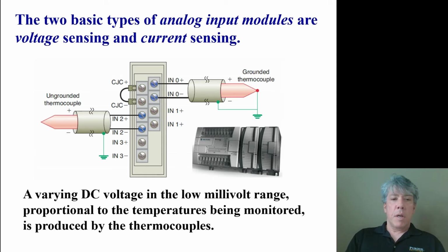It has to match. Now, sometimes the analog signal itself is converted at the PLC, sometimes it's converted somewhere else. And what I mean by that is when you have a thermocouple, for example, it generates a millivolt signal. So this millivolt signal we get from a thermocouple is not usually something that goes straight into the PLC unless the PLC has a thermocouple input module. Most times what's done is the thermocouple connects to what's called a transmitter, and the transmitter measures the millivolt signal, interprets that as a temperature, and sends it on as either a voltage or a milliamp signal to the PLC's analog input.